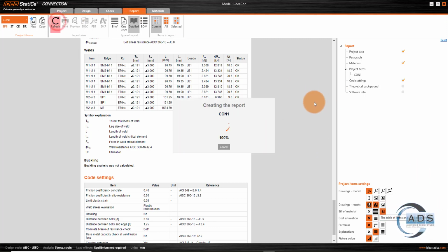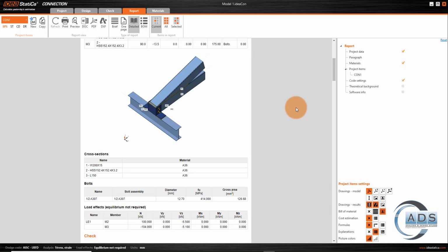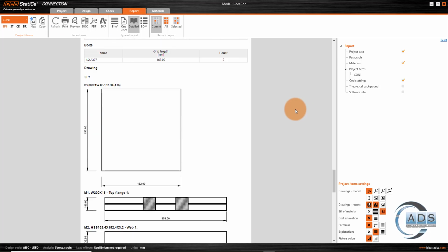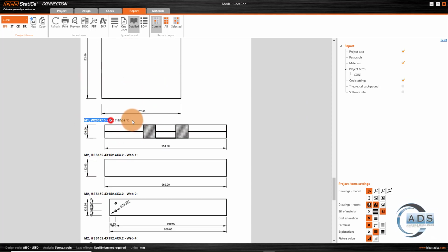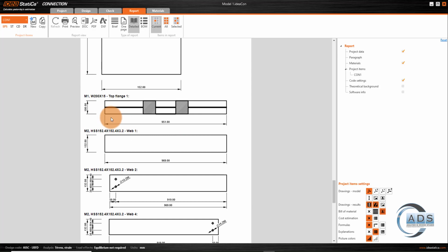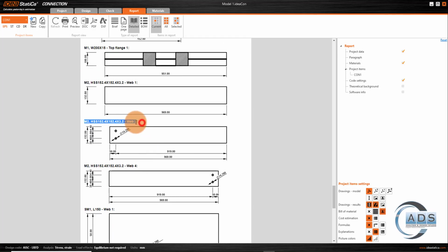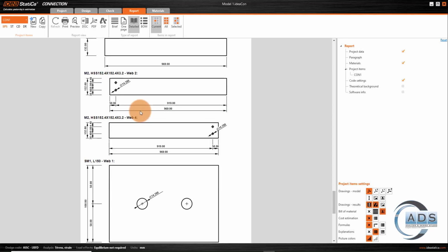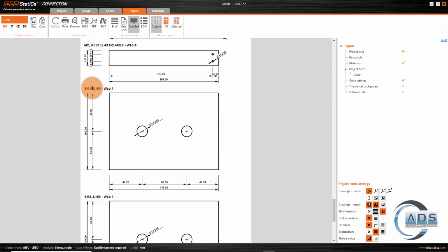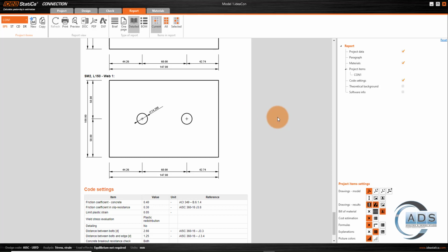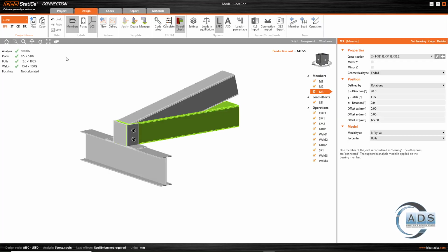And we can also click on the bill of material detailed drawing button and refresh it to view all the detailed drawings of connections, including all the lengths and offsets of the holes, welds, and all other things related to this connection. And we can also export this report to a Word file, and also export these drawings into CAD format. I'm not going into the details of this report part because I have discussed it in our previous video. So this is it for today.